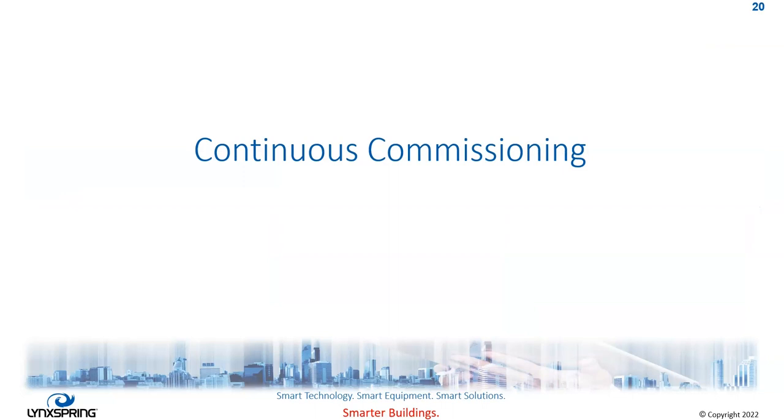Now we are going to talk about continuous commissioning. The continuous commissioning feature of the Edge VAV station is an automated program. So pretty much what happens is that it's going to commission the VAV devices monthly, and each zone that's created on the supervisor is going to commission only its zone level controllers. So each VAV is going to have its own VAV system monitor graphic to monitor the state of the commissioning operation. The graphic also contains a pop-up of the local VAV commissioning settings. And then as each VAV completes its commissioning, a report is going to be generated and sent to the supervisor.